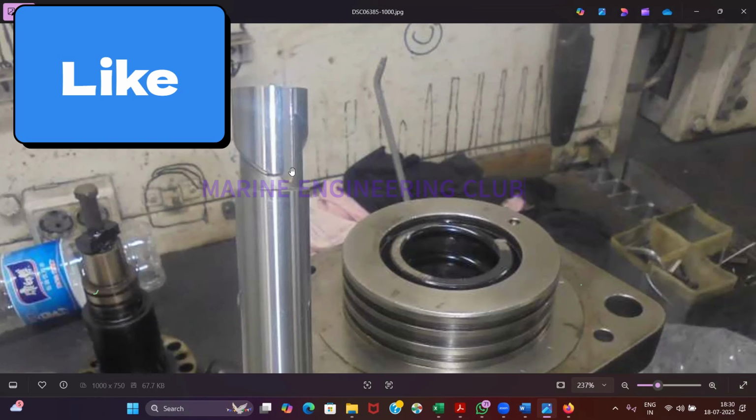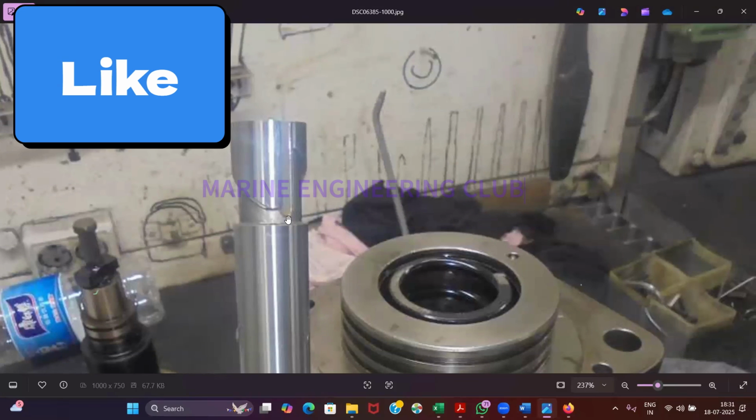If I stop my engine, what will my governor do? It will pull all the racks out. Agreed? And when it is pulling all the racks out, that means my plunger will be in this position with my helical groove at the spill port. And if it is in this position, it should stop the end of compression inside my pump, and as soon as there is no compression, there will be no fuel delivery. But as soon as you stop the engine, it does not mean your flywheel will stop at that same time. It will take some time, right? At least 30 to 35 seconds.